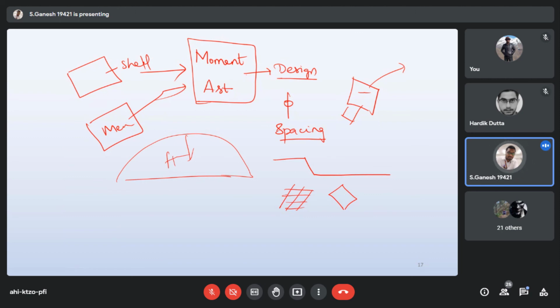So next question, about the staircase load, as a shell or membrane. Staircase slab as a membrane, we can go for, sorry, shell element. You can do the meshing for proper distribution and get your output better. But in STAAD Pro, we don't normally add a staircase. We just take the load of the staircase, apply it to the beams where it is going to rest, and design that beam with respect to the staircase so that it will take care of the load distribution. That is a part we do as a shortcut.